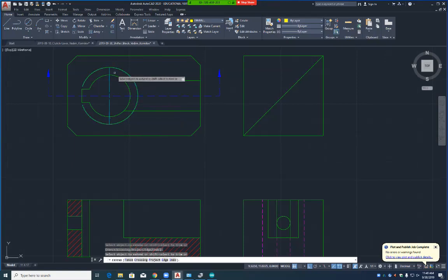Okay, now, question for you. So this is a 1/2 inch, right? To get my up and down, where am I going to go a 1/2 inch away from what? From here? So if I put a linear dimension now for the center line, from here to here, see, that didn't work there. If I put this out a 1/2 inch right there, does that look correct? Should be a 1/2 inch off our cutting.